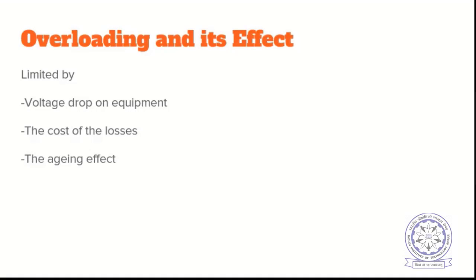Overloading and its effects. Basically, overloading is limited by these three conditions. First, voltage drop on equipment. If we overload a transformer or any power equipment and I increases, the voltage will eventually drop because the leakage reactance will cause a drop.